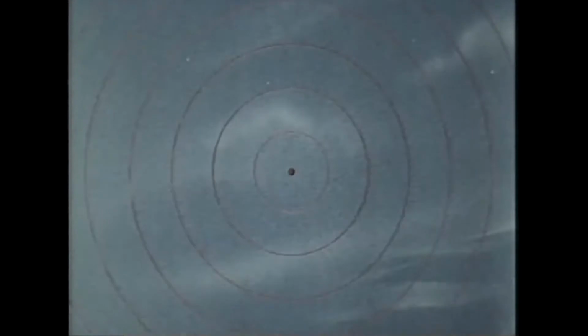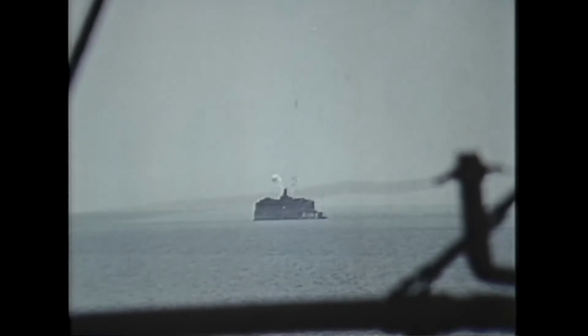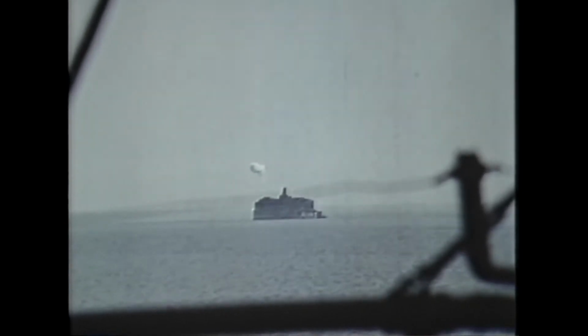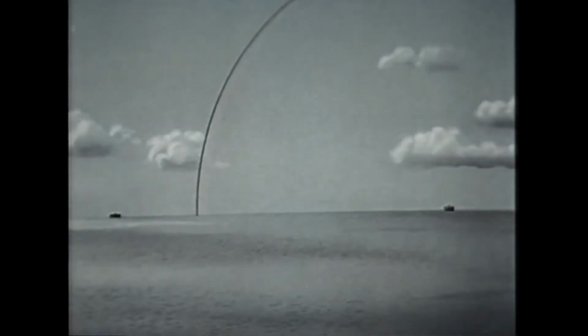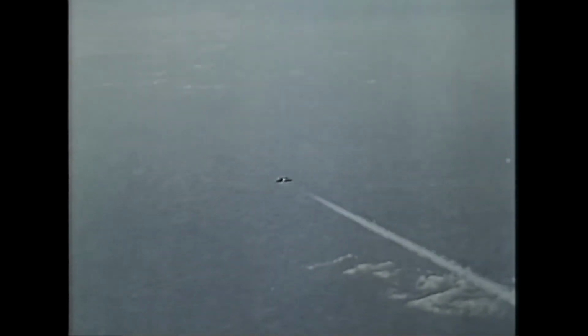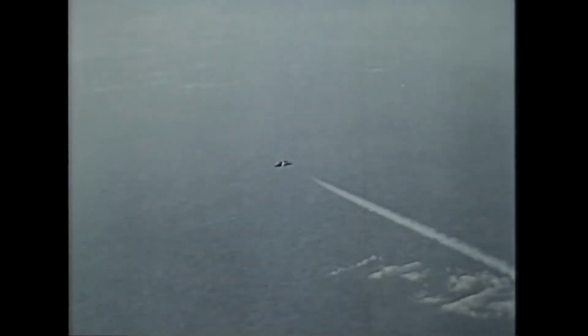Not all pressure waves are audible, but all small disturbances, audible or not, travel outward at the speed of sound. Watch this explosion. A mile away, its sound takes 5 seconds to reach us. At sea level, sound travels at about 760 miles an hour. But the speed depends on the temperature of the air, which drops as we climb upward. In the stratosphere, which begins at about 36,000 feet, the speed of sound is only about 660 miles an hour because of the lower temperature.